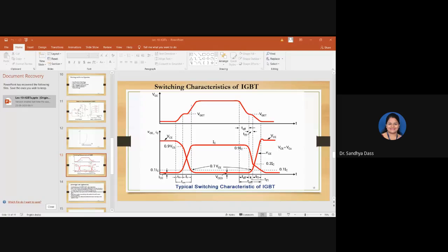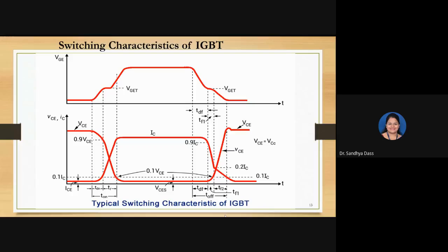Now go back and look at the waveform there. What are you able to interpret? So what is T on? From our previous sessions, what is T on? It is the total time for the device to turn on, right? It is given by summation of delay time plus rise time, isn't it? It is not changing.